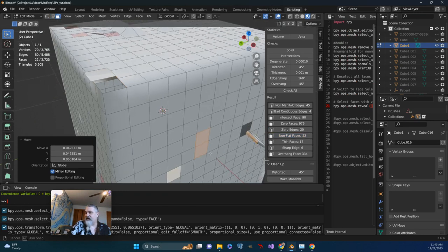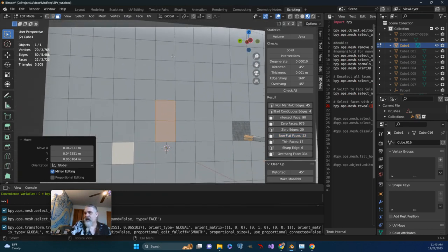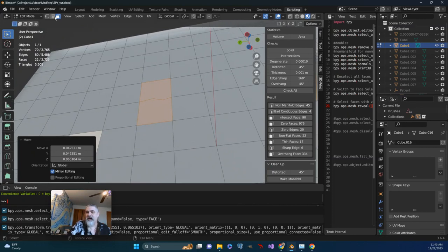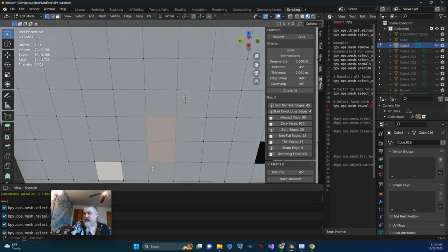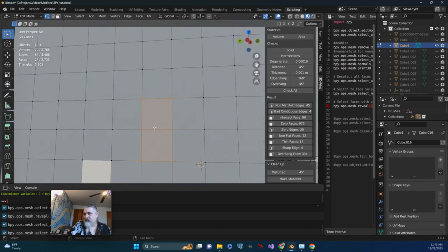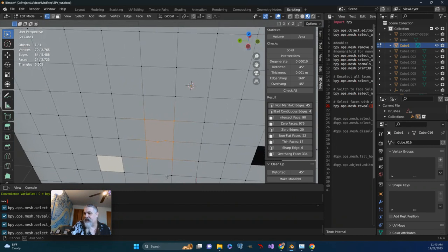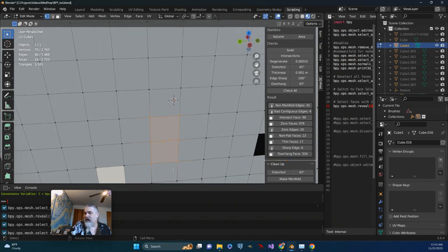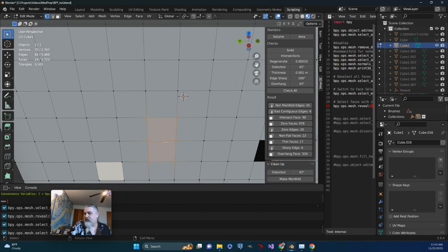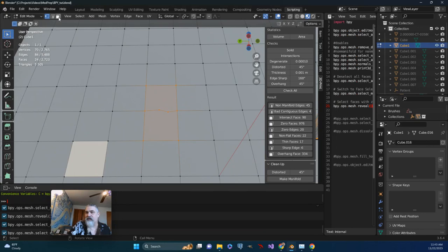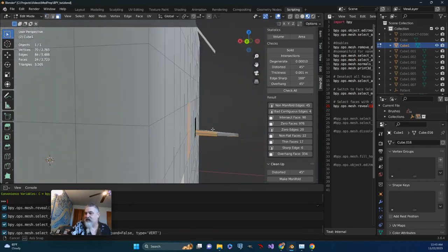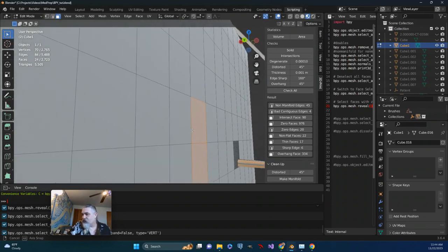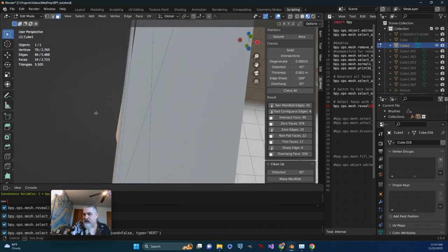Non-flat faces. I've got a couple right down here, and it's basically impossible geometry. If we look at the vertices, you can see that this is a single face, but these vertices don't exist on the same plane. And that in essence creates kind of a curve where there shouldn't be a curve. You can kind of see it if we're in face select mode and we start moving around, that these things don't quite jive or match up. There's some wonkiness happening there that can't exist in the real world.